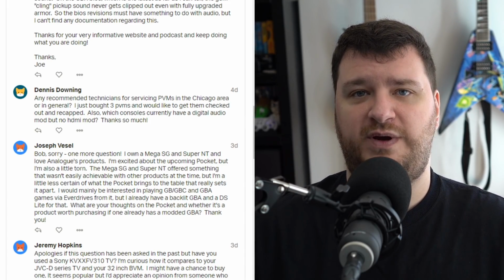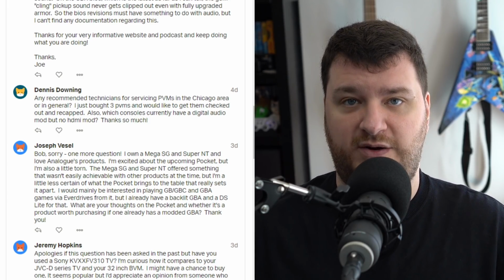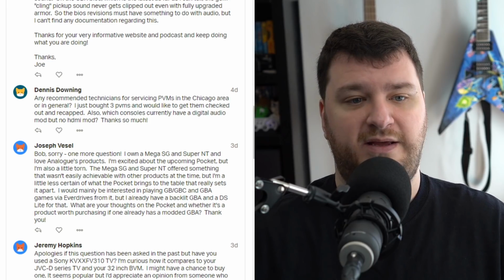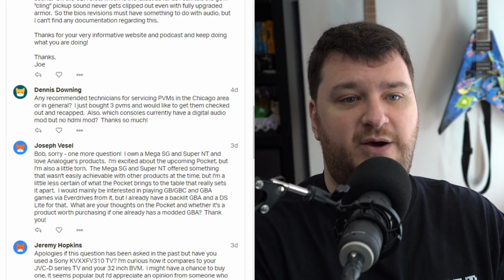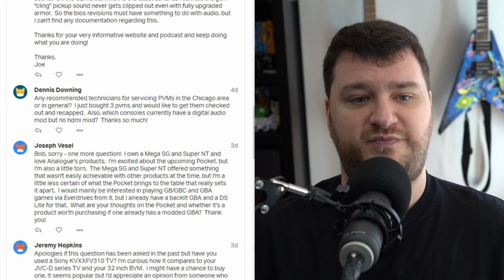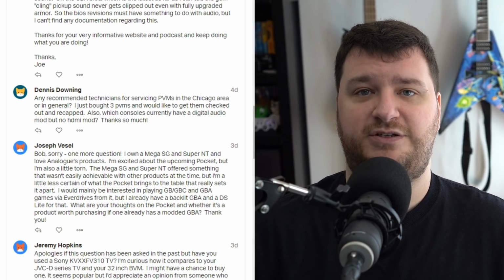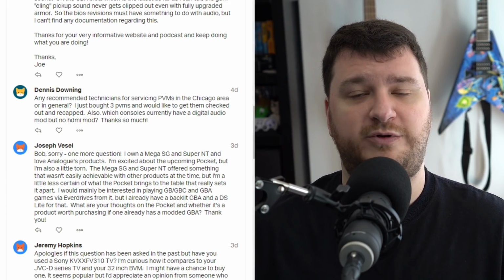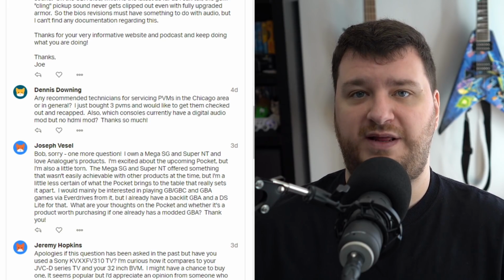But there's quite a few, and I think a lot of them use the same sound chip, so it's the same mod in all of them as well, which is pretty handy. You're basically just tapping the digital signals, putting them through a small circuit and out an output connector. If you have a good stereo, I find digital audio to be better in almost every case, simply because you don't have any ground noise or hum or anything like that.